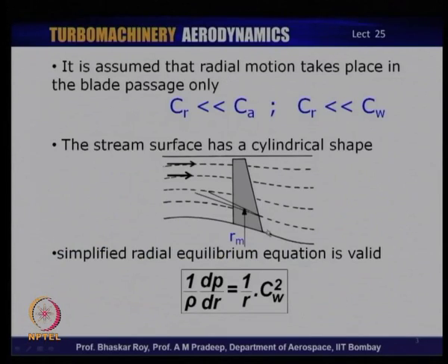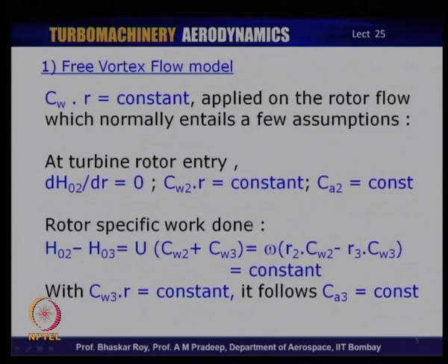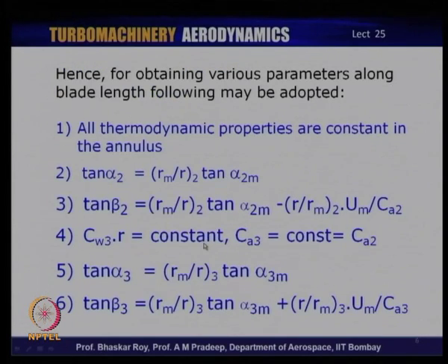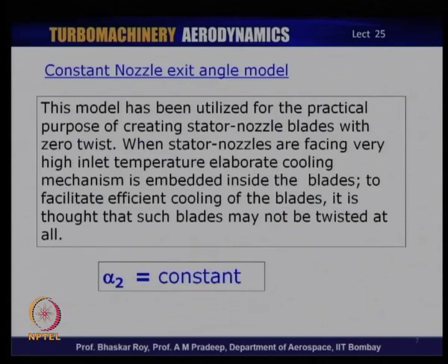If you look at the drawing here, it tells you very clearly that at the exit side the radial variation is far more than at the leading edge or the entry of the axial flow turbine rotor. So, those are the simple things that we can get out of free vortex design, and as I mentioned, it does give us a very simple flow feature. However, it does create a complex, somewhat twisted and more complex blade shape.